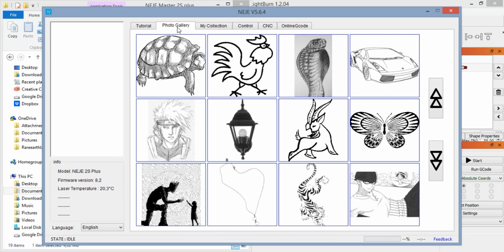If you had to think of a laser beam that's a fraction of a millimeter thick, it would basically engrave a line, move to the next one, engrave another line. It takes really long. In the photo gallery, the instructions are not particularly good for the software, but this seems to be a raster engrave. Typically you know it's a raster engrave if there are multiple different shades in the same picture. It could be grayscale, it could be filled in. It would be very difficult to do this as a vector, for instance.